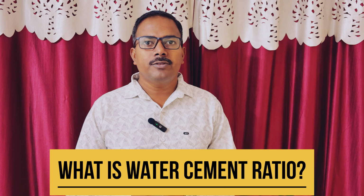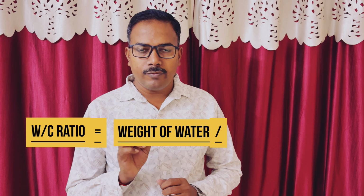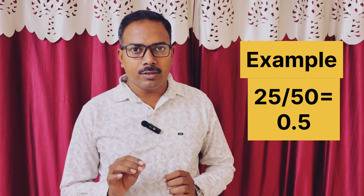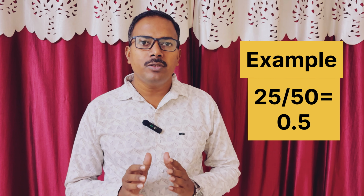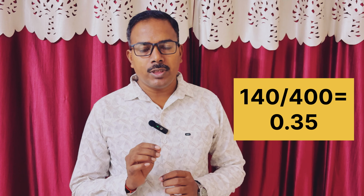So the first question that arises in our mind is, what is the water cement ratio? Water cement ratio is the ratio of the weight of water to the weight of cement which is used in concrete mix design. For example, if we are using 25 kg of water and 50 kg of cement in a mix, the water cement ratio will be 25 divided by 50, which is 0.5. So the water cement ratio is 0.5. For better understanding, if we are using 140 kg of water and 400 kg of cement in a concrete mix, the water cement ratio will be 140 divided by 400, which is 0.35.